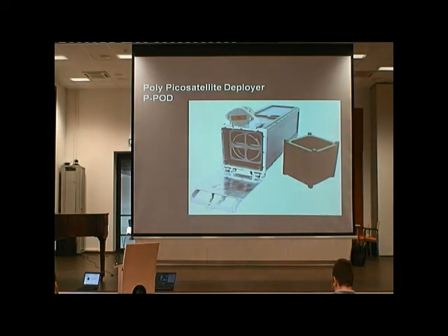Part of the standard is this box here, and this is called PBOD. It's the original launch deployer for a CubeSat. And this is actually maybe even the most important part of the standard, because nowadays all the launcher companies, they have this box, and this box is safe. The CubeSat, even built by students, fits inside, and it's totally shielded from all the other payloads.